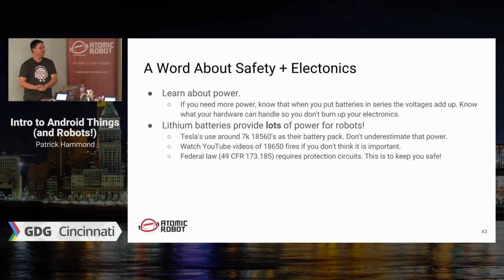So, word about safety: don't do what I've done. I have fried lots and lots of circuit boards recently. One last night. So, learn about how power works. If you put batteries in series together, the voltages add up, and when they add up, then electronics like to go, poof, and you get the burnt silicon smell.